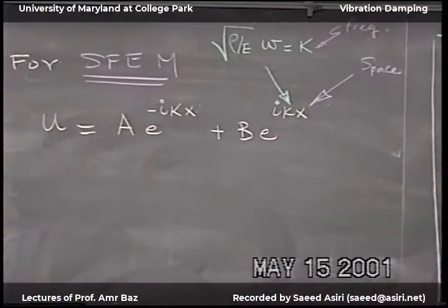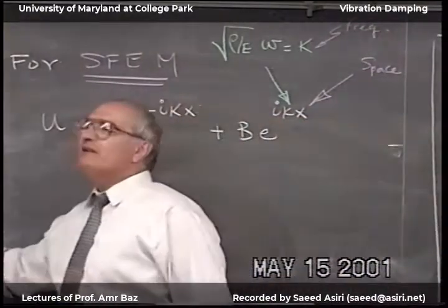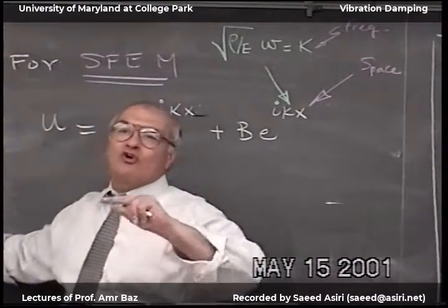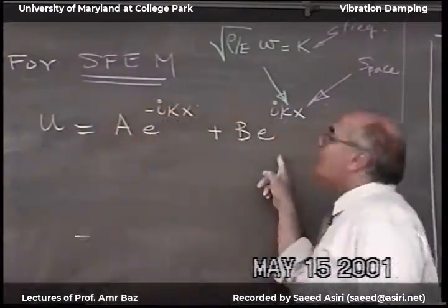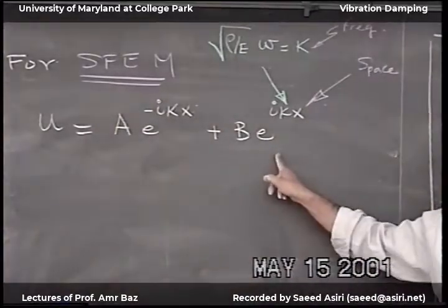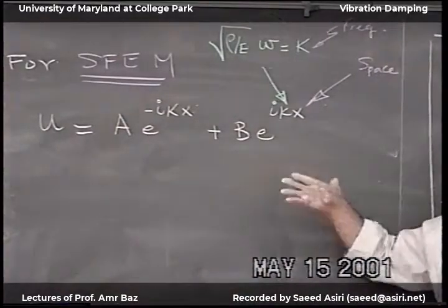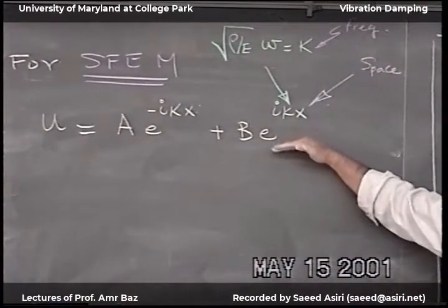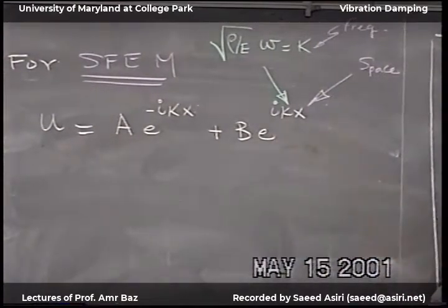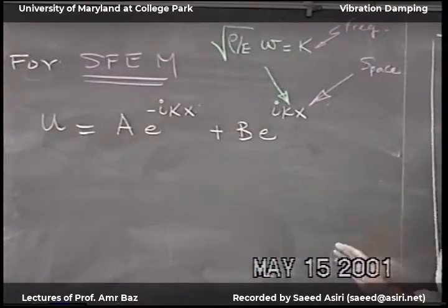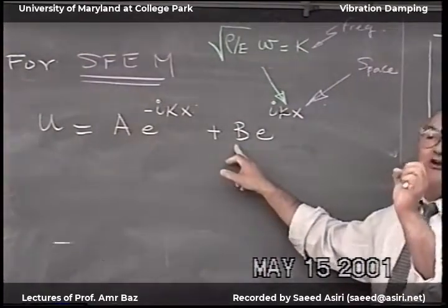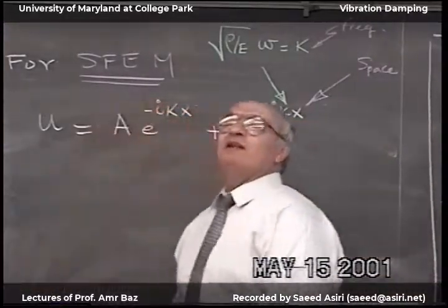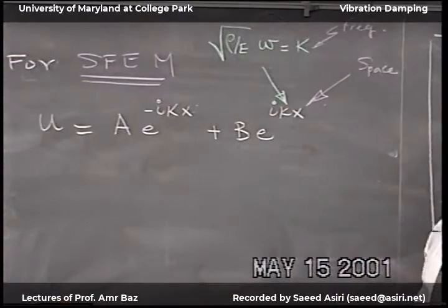And also, I'm not using a simple linear function. I could, okay, but this is a very coarse approximation. I'm using the exact shape of how u varies along a rod, because we know that this is the exact solution of the partial differential equation. So automatically you expect this to be super accurate compared to this very simple linear interpolating function or shape function.